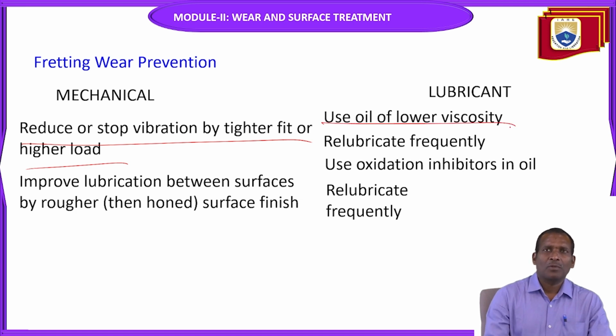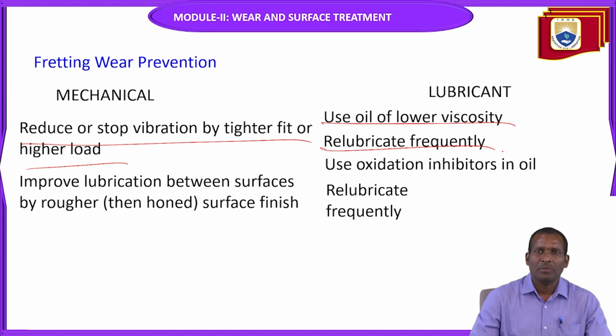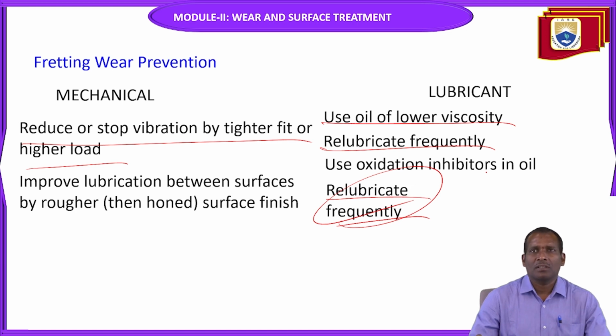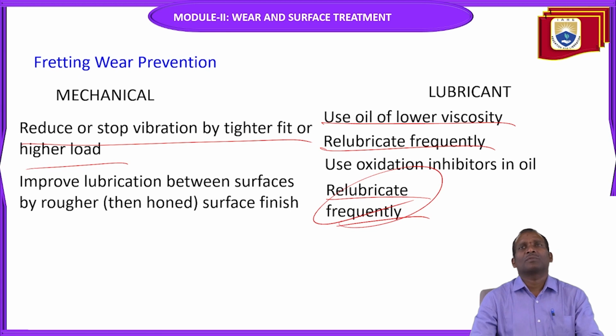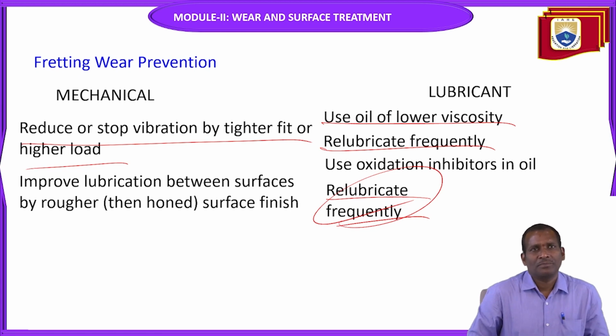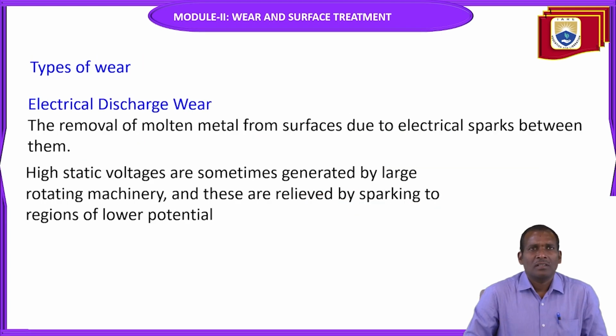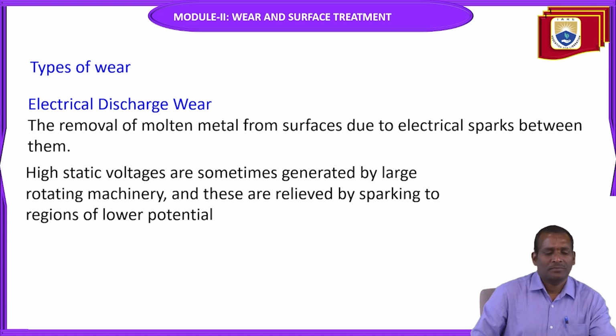Use oil of lower viscosity. Re-lubricate frequently. Use oxidation inhibitors in oil. So use oxidation inhibitors and then use lower viscosity oil for this fretting wear only, to prevent this type of wear. Next one is electrical discharge wear.